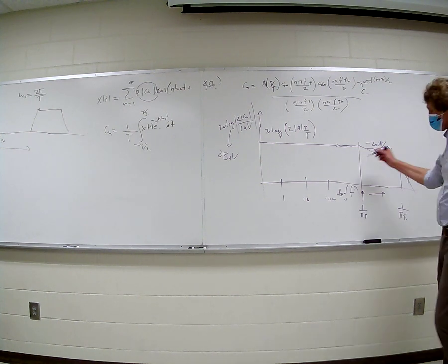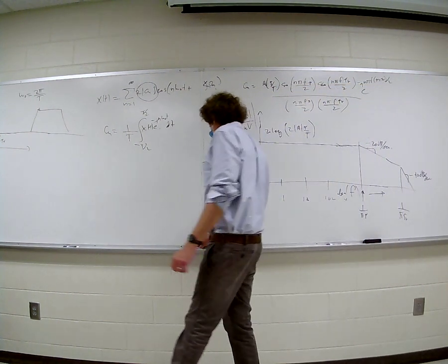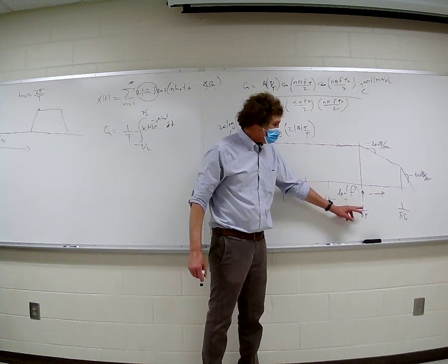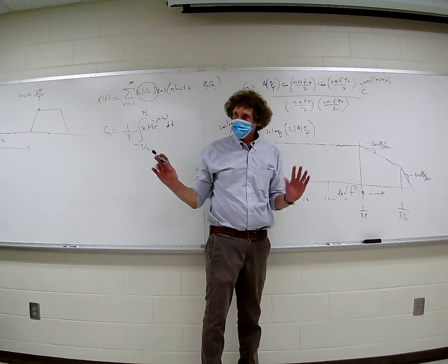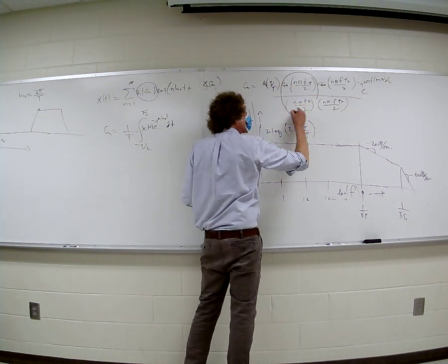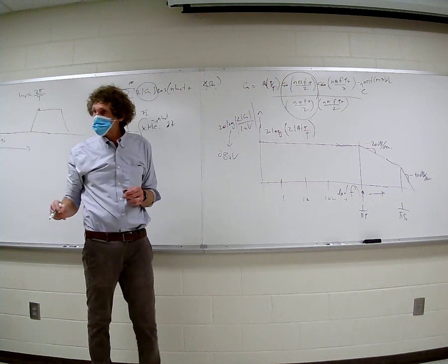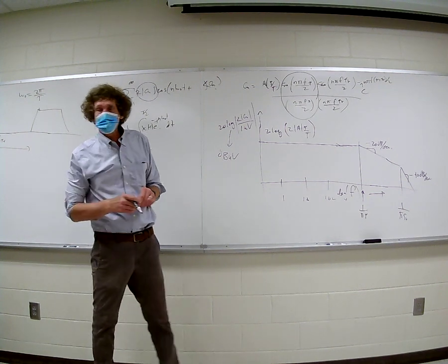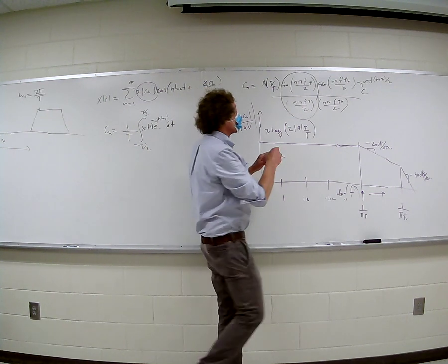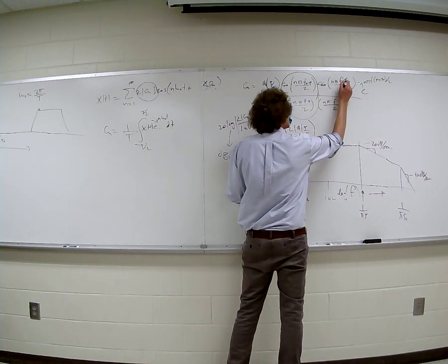Now this is the envelope. What I wanted to say too is, last time I said 1 over tau, but I knew it was 1 over pi tau. The problem is this: when you look at this right here, that's a sinc function, what I just circled. Do you see it, everybody? Now, it's when the lower argument goes to 1, right here. And this would be f naught here, by the way.